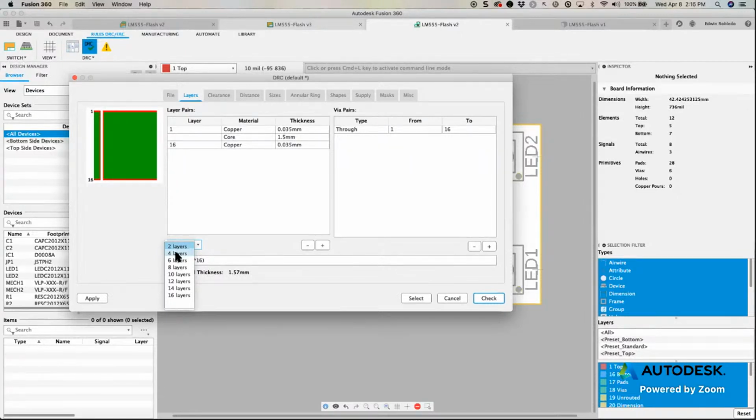Well, the main reason is that there's no extra effort in making a 4-layer versus a 3. In fact, it probably would require more effort for them to not use pairs, because when it's built up like a sandwich, you have that middle part, the core, which has copper on both sides. Then if you're going to build up a proper stack-up, you need to keep putting layers on both sides for everything to be balanced and stable.